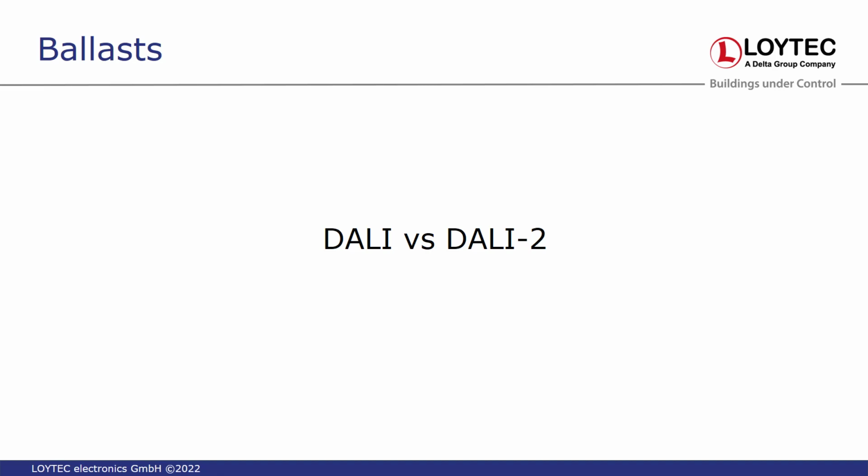Yes, yes. Actually, maybe I did understand you wrong. For the LDALI, it doesn't matter. The LDALI works with DALI 1 and DALI 2 ballasts the same way, so this is not a problem. Special handling for the standards only comes in when you talk about occupancy sensors and other kinds of sensors.